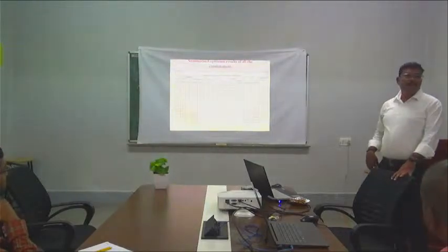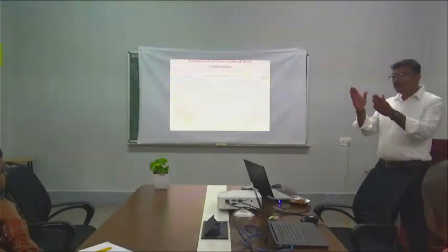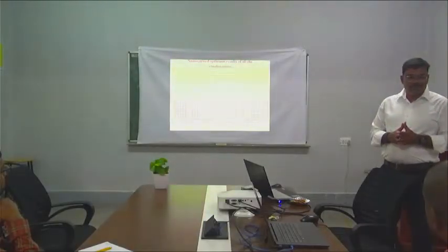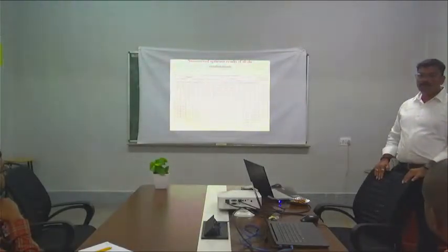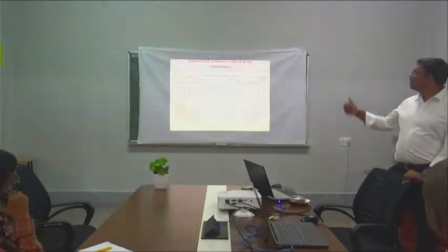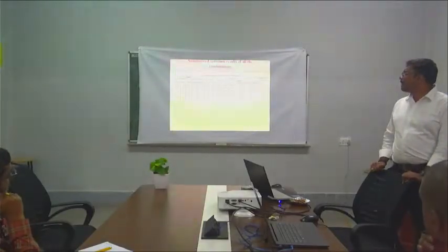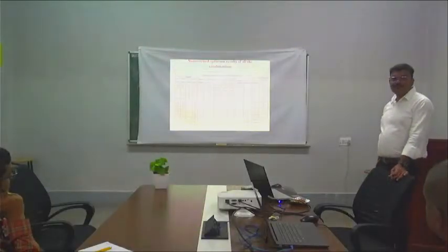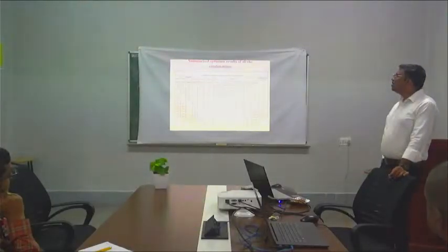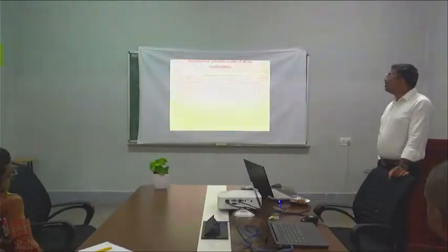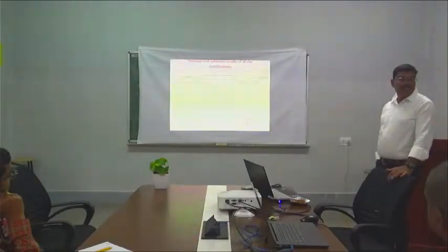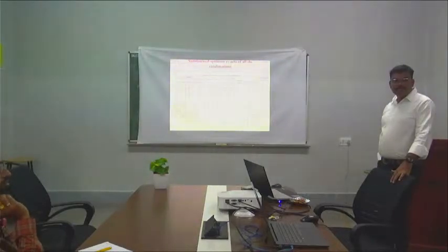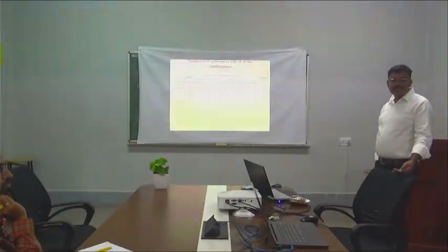At the time of starting, what I have done, I just considered some load, some DGs, solar PV or wind or whatever it is. I wanted to compare. What is the LCOE of the first case? 0.195 dollars per kilowatt-hour. The analysis is done with the objective to minimize the LCOE. LCOE should be less.